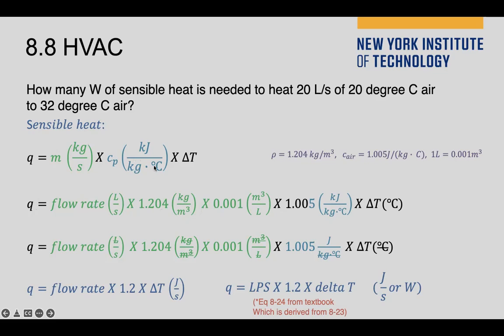And the specific heat capacity of the air is equal to 1.005, times the temperature difference. So you can simply see that if I cancel out some of the units, the remaining unit of this equation is Joule over the time, the second.